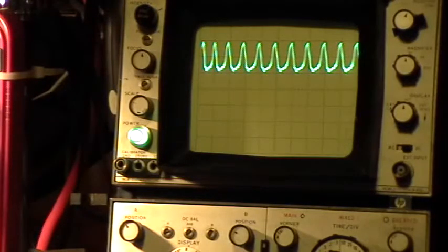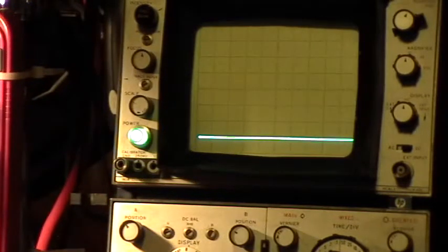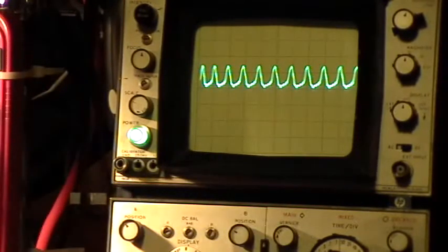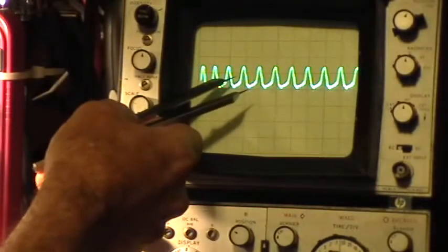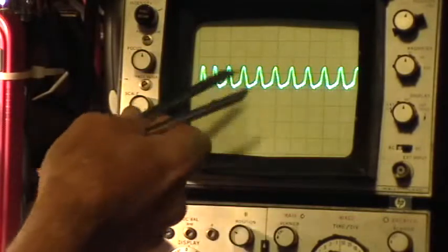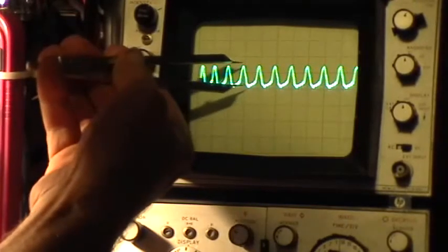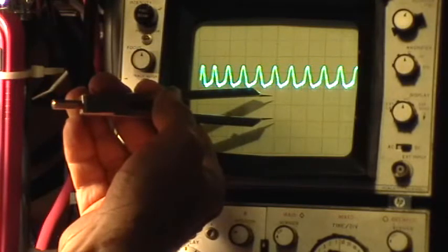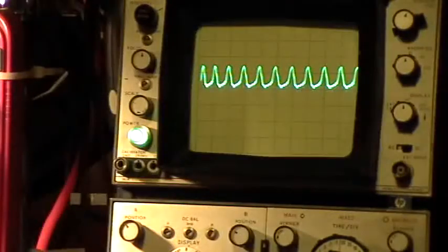Now I'm going to move down one battery, to the 36 volt positive pole right there. Let's reestablish trigger. Like that. Now we're at 10, 20, 36, and the oscillations are going back and forth around that 36 point. The amplitude of the oscillations is now 1.4 divisions at 10 volts per division, so it's 14 volts now, peak to peak.